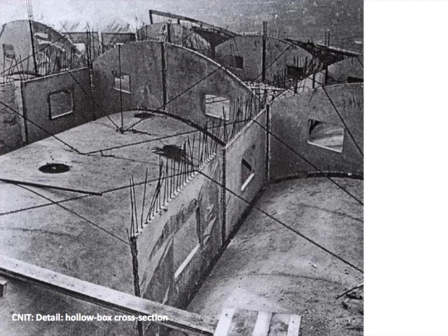The shape of the shell's cross-section is a hollow box, consisting of two 60mm thick skins forming the outer surfaces, separated by 60mm thick diaphragms to give an overall depth of 1.5 meters. This is a highly efficient shape of cross-section for the resistance of compression, where the possibility of buckling, a bending phenomenon, has to be allowed for. The slight corrugation of the shell surfaces provides efficient resistance to any tendency for local bending or buckling to occur.